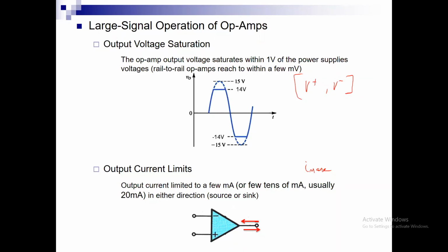Okay, and let us say that if I tell you that I have Vn here A times sine omega t, and that the gain is AV, and I end up with V out, which is 5 volt. Okay, it may pass this criteria, but may fail this criteria depending on the R load which it is feeding, right? And the voltage is voltage, but the R load will determine my I out. It may fail both, or it may pass both, or fail one of them, right? So these are independent.